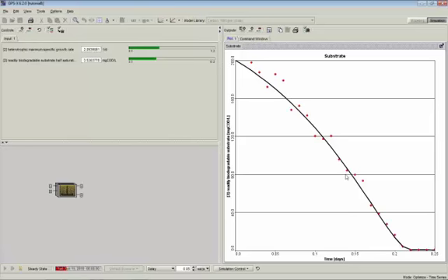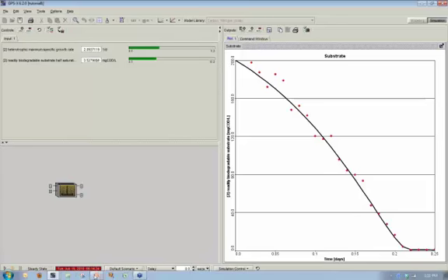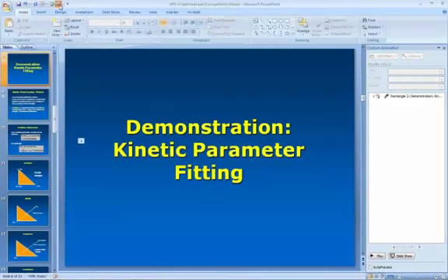And you can see here pretty much we're plotting the same line over and over again with very small changes. And so this is what the optimizer feature can do for us. I'm going to set it up so that it finishes up its last run there. And we can see that now it's fit that line about the best that you're going to be able to do in this case. So that's a good parameter fitting exercise. And you can see how originally from our original guess of, I think it was 2 and 2.5 or something like that, we've now got a much better estimation and, of course, a much better fit. Okay, so let's go back to our slides